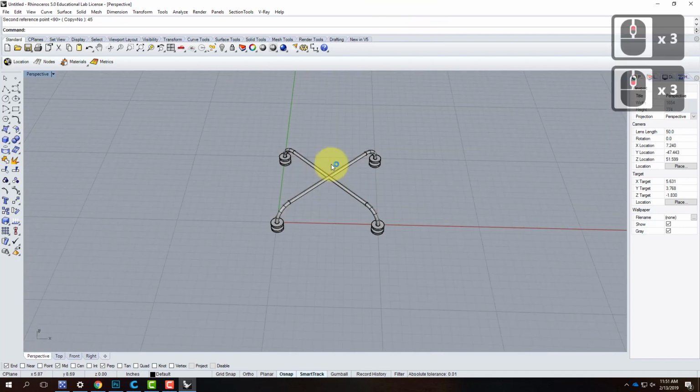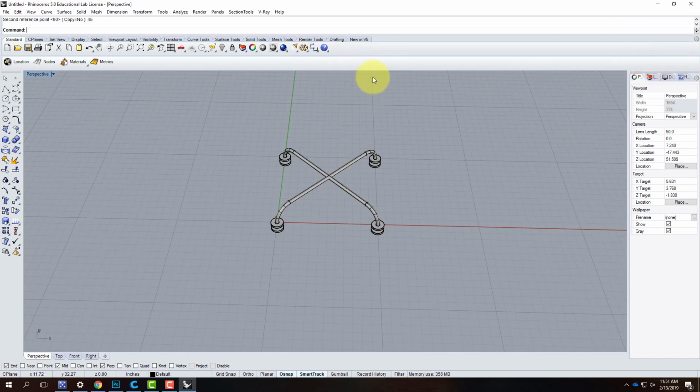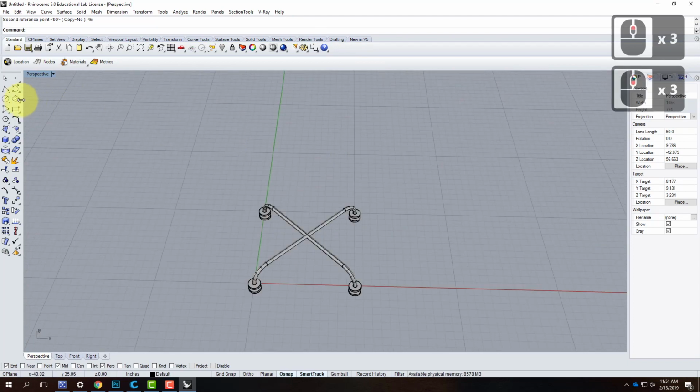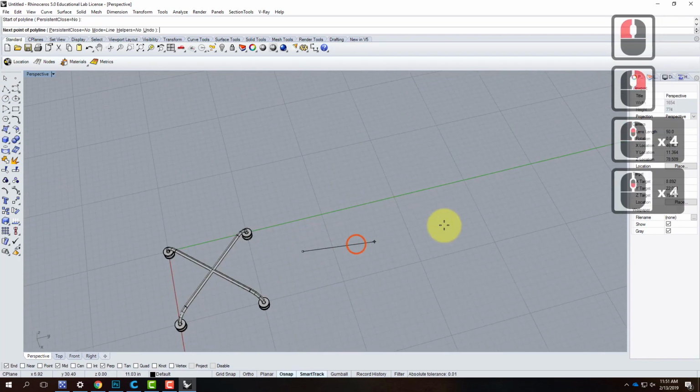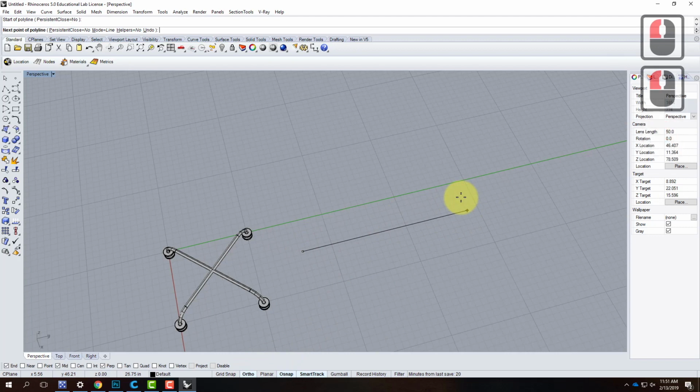Essentially what we're building is the rod that goes off the top of this, and then the little donut that goes on the end of the rod. So I'm going to go ahead and build it over here flat, and then I'll end up rotating it afterward. So I'll start here with a polyline. Turn on ortho here for a second. That is the length of the little rod, which is 2 feet. So I'll go ahead and type in 2 feet.